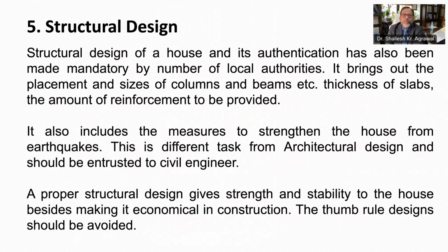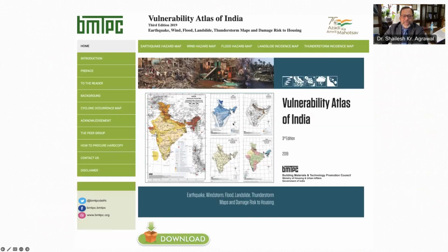It is also important to know the hazard scenario of your location in terms of earthquakes, flood, wind, cyclones, and incorporate the provisions accordingly. For knowing the hazard scenario, BMTPC's Vulnerability Atlas of India can be referred to, which is available online.